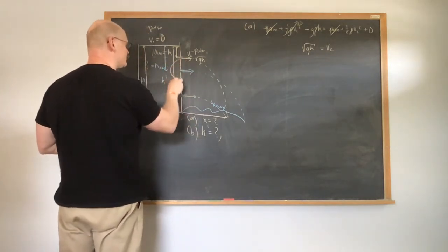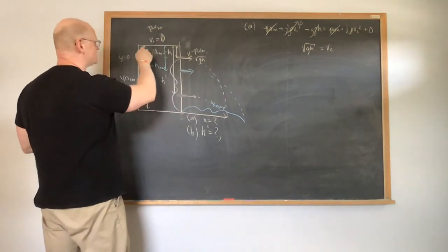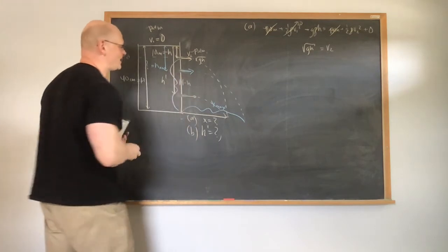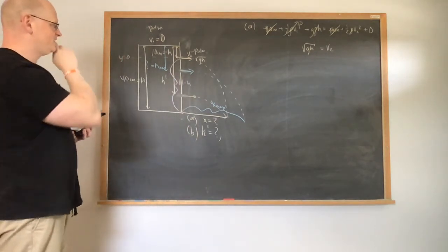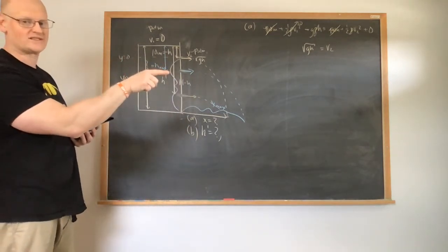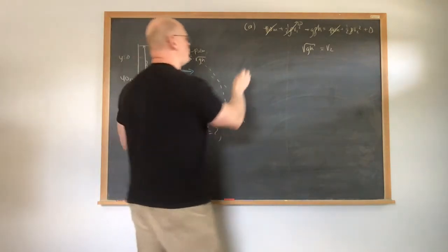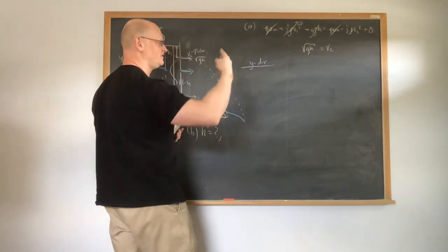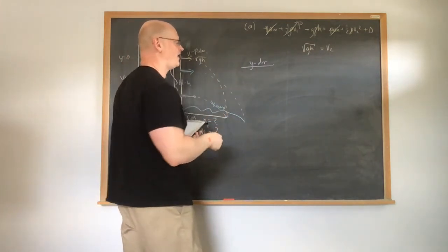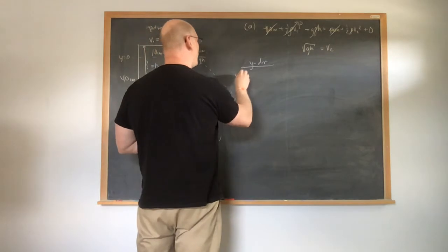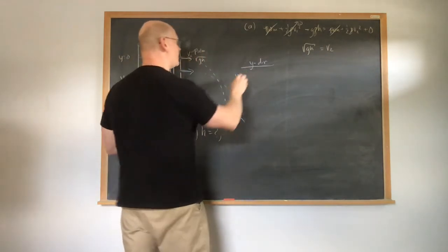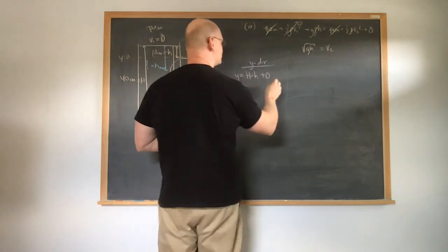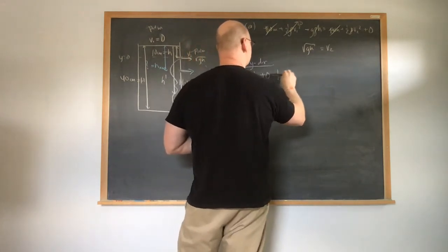So we know the distance that this is going to fall from here is going to be the same thing as capital H minus little h. So this is capital H minus little h of distance. We also know that water is coming out only horizontally. So in the y direction, there is no portion of velocity in that direction. So here we can say that y then is equal to the initial height, which is going to be our H minus h, plus the initial velocity, which is 0, minus 1/2 gt squared.